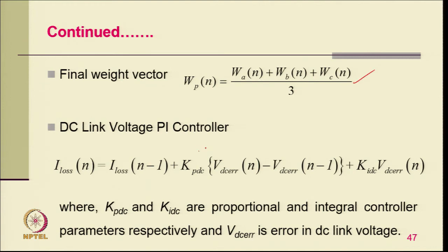And of course, for the DC link voltage controller, with the DC link voltage error, you can put the PI control, that also has to come as active power from the supply. This is for the load, and this is for what you can call the loss in the converter, interfacing inductor, and dielectric capacitors on the DC link line.